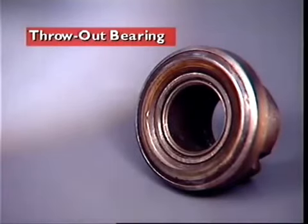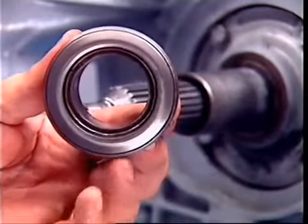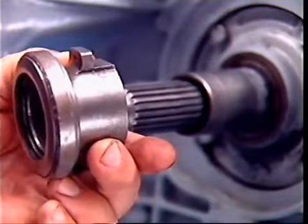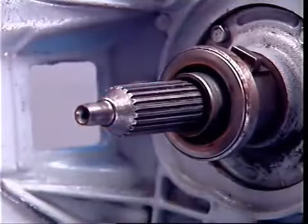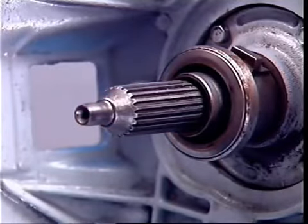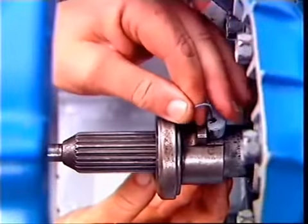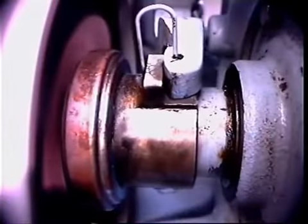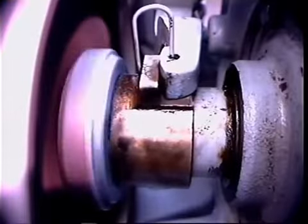This section examines the throwout or release bearing. The clutch release bearing can be a thrust-type angular contact ball bearing supported on a carrier. It slides on a hub or sleeve extending from the front of the transmission. The bearing carrier locates on the clutch release fork. Moving the fork brings the bearing thrust face into contact with the pressure plate fingers.